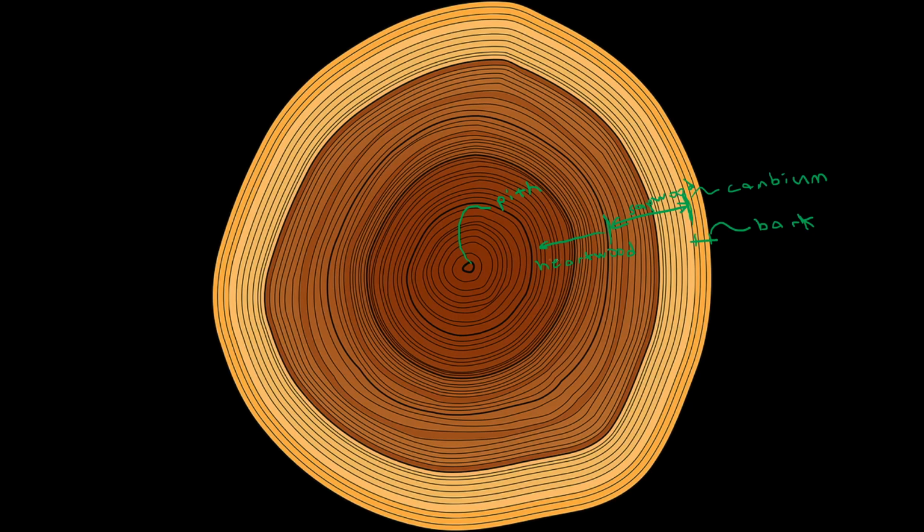But once it's inside the heartwood, there is no more living tree there, so the only way for the tree to defend against intrusion there, and termites and things like that, is via chemical resistance. So as the cambium moves out, it deposits chemicals inside the old dying wood. As the cambium cells die off, they release chemicals that serve as preservatives in the interior wood, and that is why you end up with darker wood inside the interior of the tree. That darker color is preservative chemicals released by the actively growing cells as they die off and the growth wave moves outward.